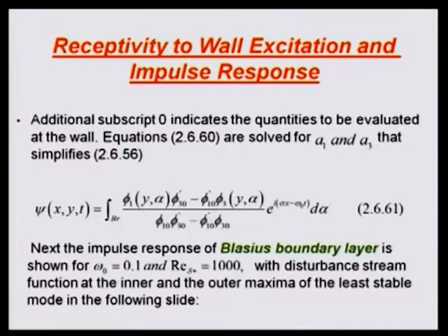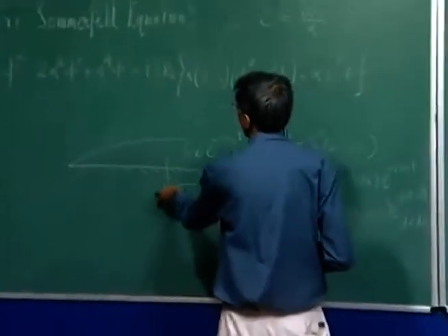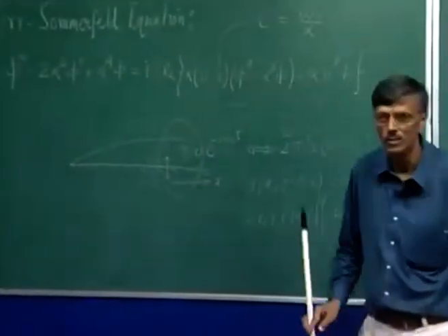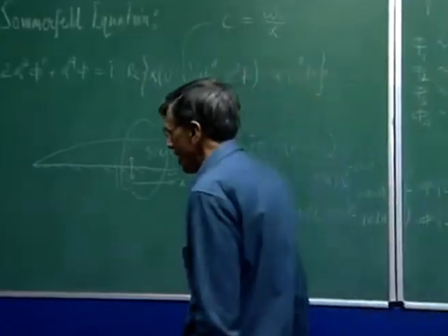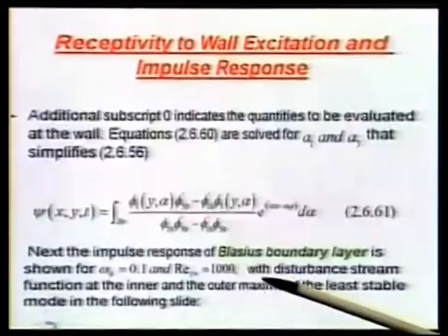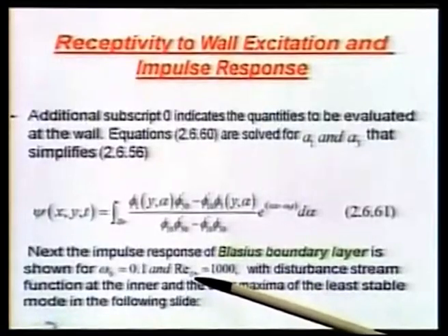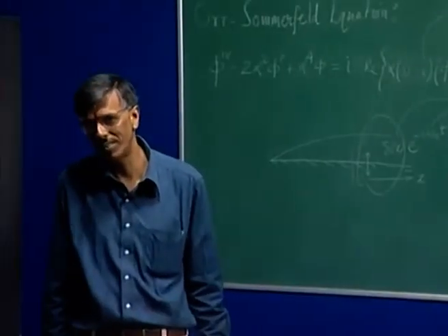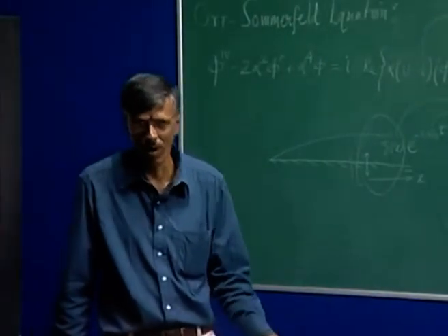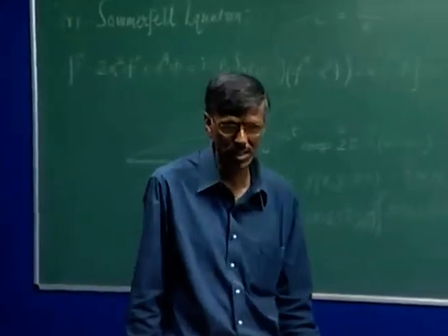We take a Blasius boundary layer and we take a Reynolds number of 1000, that would perhaps contribute to somewhere here. So, where we have some kind of a parallel boundary layer, this delta star relates to the displacement thickness, okay. And we have already seen that Reynolds number of 520 is about the point where flow becomes first critical.